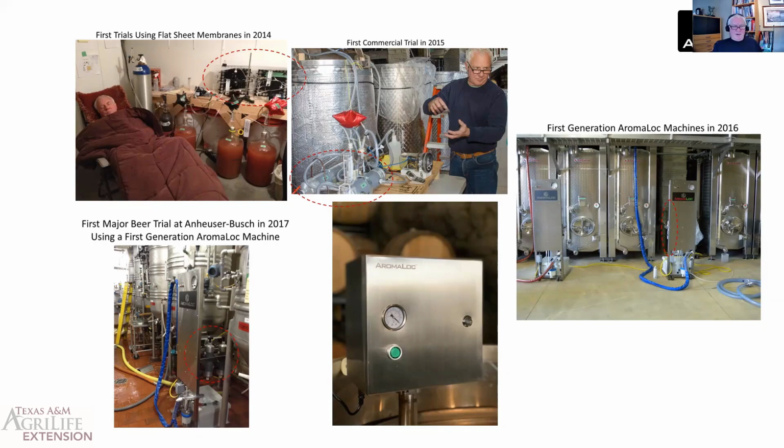The physics are almost the same, whether it's CO2 or nitrogen carrying the aromas. The aromas will go across our membrane and be pumped back to the headspace. Now, CO2 is more soluble in the membrane and it diffuses more than nitrogen would. So we probably wouldn't get the volume of nitrogen going across the membrane, but we would get some.